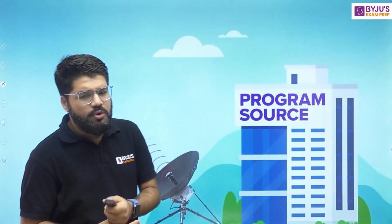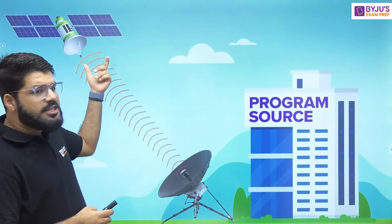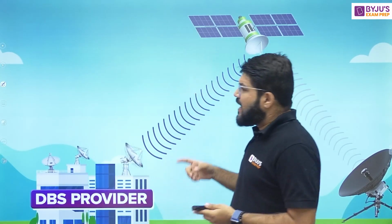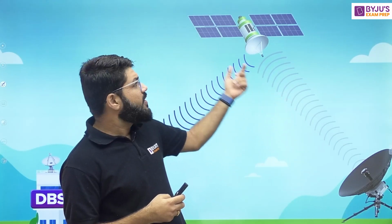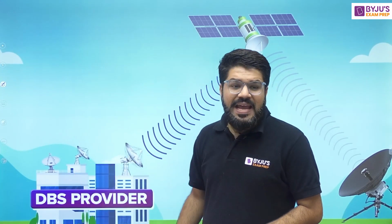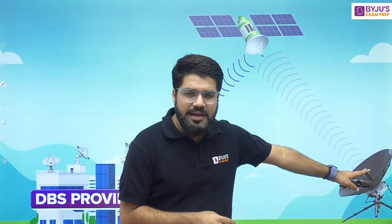Now for this, let's have a look into this. For this, the program source is going to transmit their signal onto the transponder which it has rented, and that transponder is in the geostationary orbit. Now the complete information given by the program source is available at a single point, and any DBS provider, be it Tata Sky or Dish, can access this information by its respective receiving antenna. But before that, it has to make an agreement with the corresponding channel.